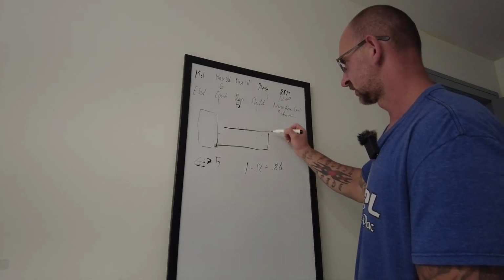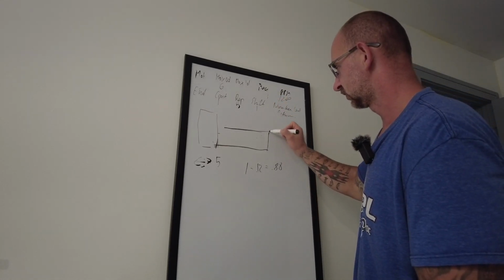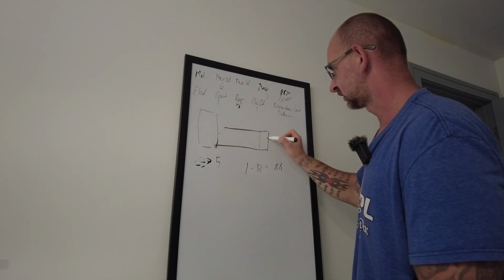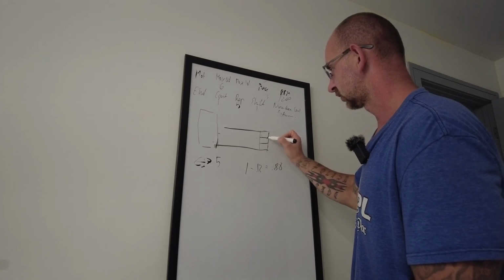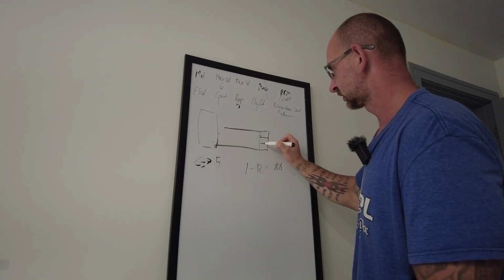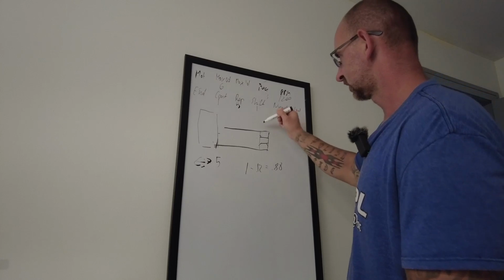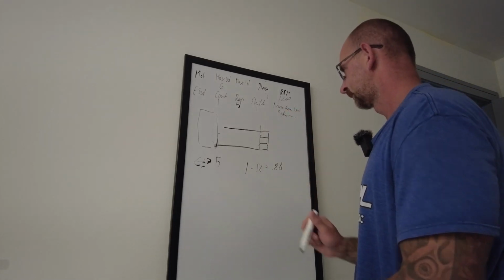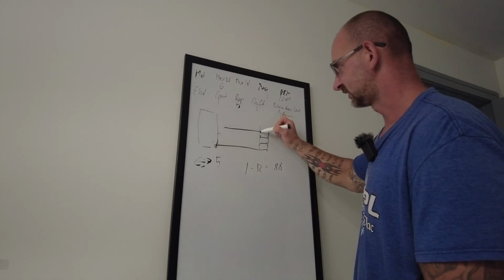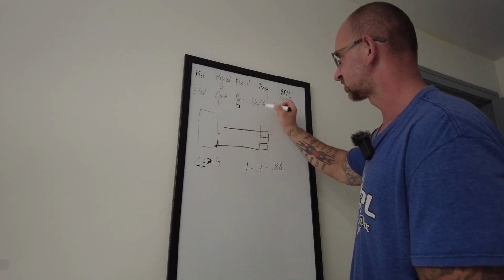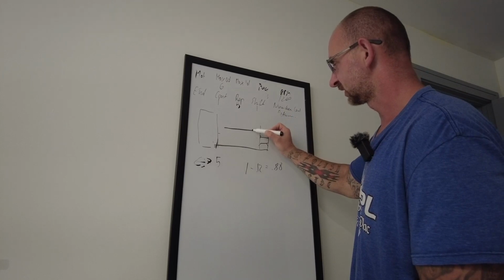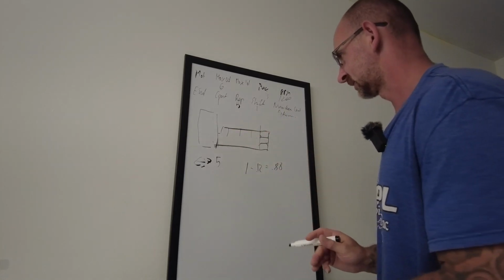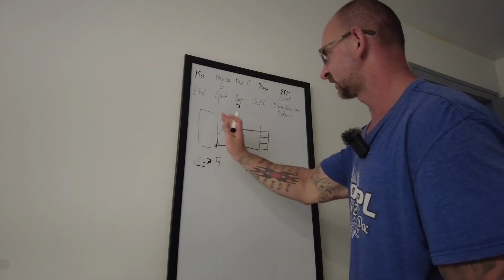So what the machine's going to do is, you do OD turning, you do facing, maybe you do drilling, you throw a chamfer here, a chamfer here, and all these things. Then you come up with a cutoff, boom, boom, boom, the part falls off, right? Then automatically this becomes your 0, and the machine shifts that 1 inch. Now we're making the same thing over here, and over here. So technically it's going to repeat the same thing 5 times.